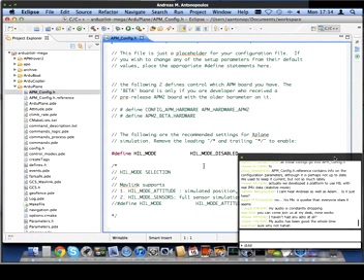You would make these changes before compiling, and then when you compile the code, based on the definitions in here, it will enable or disable certain sections. So for example, one of those is to disable hardware in the loop mode. And you can see that's disabled here with this hash define.